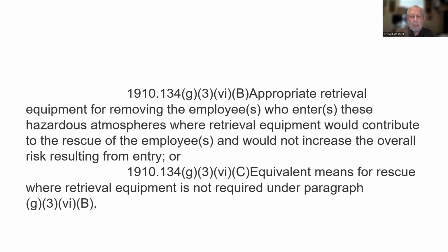What we did at OK Foods, fortunately, we never had to do this in a live situation, but with training, we had to have 2 people fully dressed up in SCBAs and full level A suits, to go into a potential ammonia release. And we had to have 2 people fully ready to go, backing them up right outside the door. Now, ammonia IDLH is 300 parts per million. That's going to be achieved pretty quickly in any significant ammonia release. So they're going to be in an IDLH.